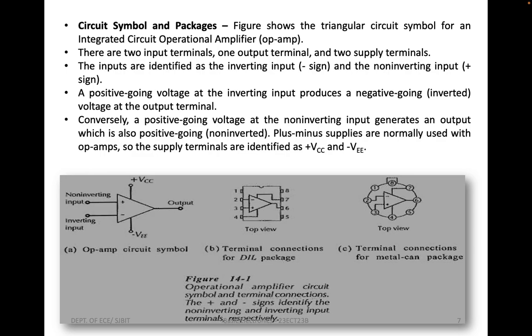Because of this high voltage gain, externally connected resistors must be employed to provide negative feedback. So the design of these IC op-amp circuits involves determination of suitable values for the external components. The design calculations are usually much simpler than for discrete component circuits.